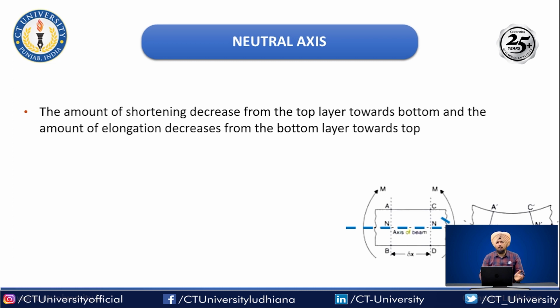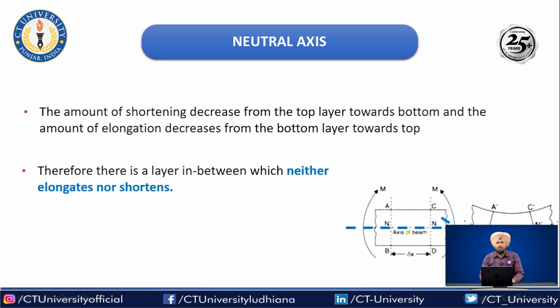So before and after, the length of this neutral axis will remain the same. And this is a very important concept to note for the upcoming equation, because we are going to use the length of this layer in the upcoming slides, right? And this layer is termed as the neutral axis or neutral layer also.